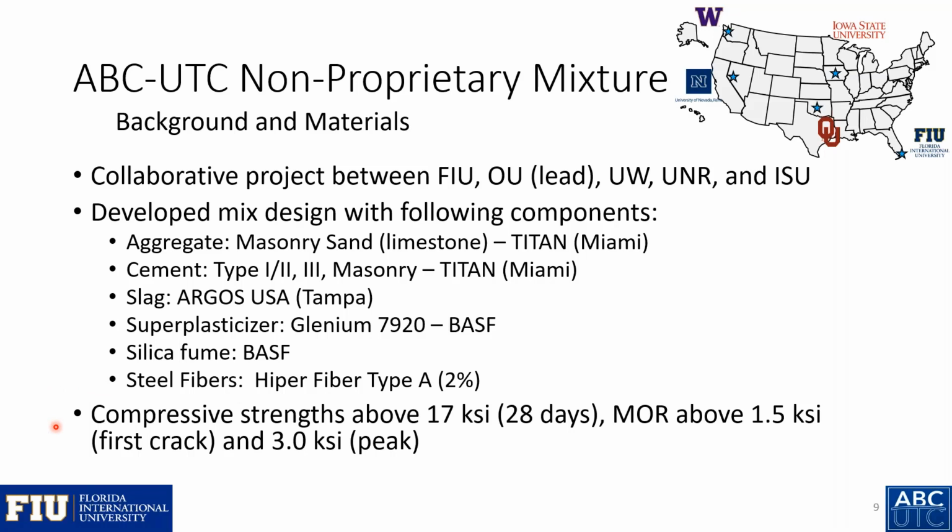The compressive strengths that we saw were around 17 or 18 KSI to 20 or so without any heat curing. And we did modulus of rupture tests and found with the final mixes a first crack above 1.5 and the peak above 3.